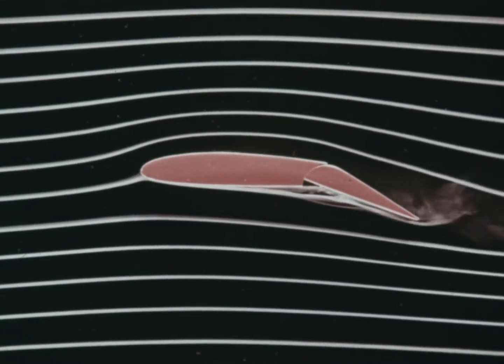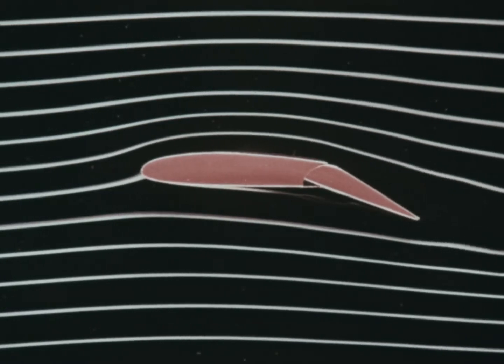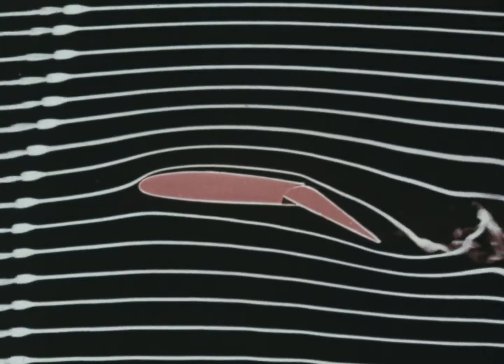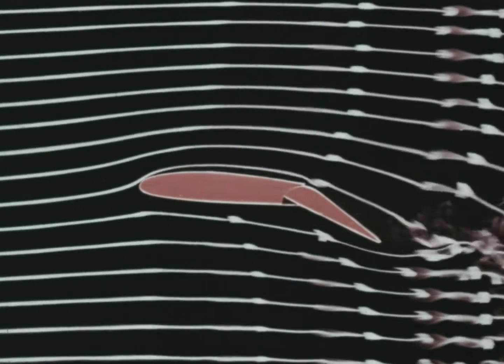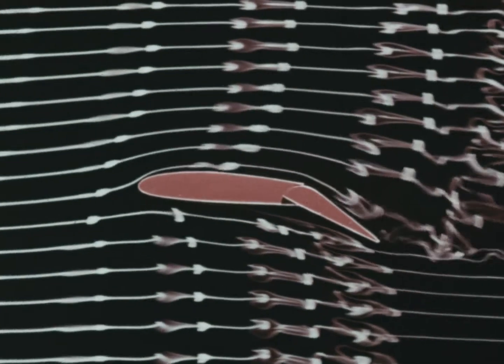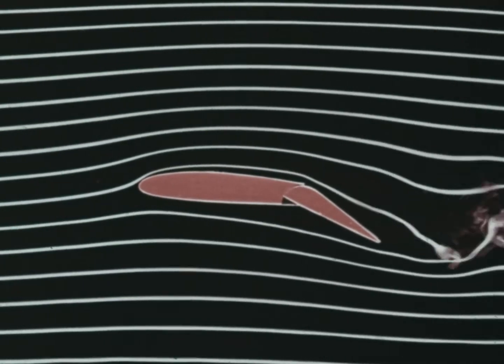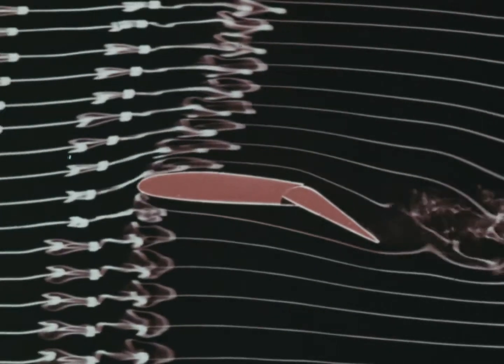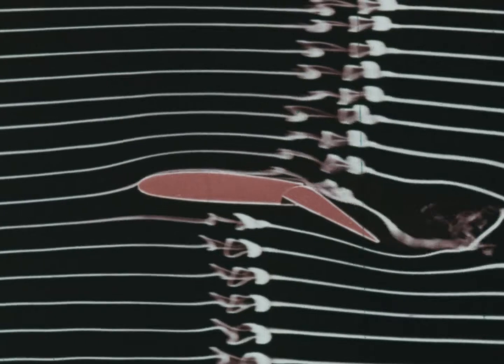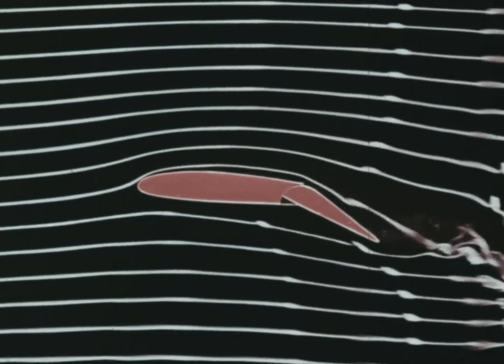This increases the camber of the wing over part of its span. The upper surface of the wing now has even greater curvature, and the airflow therefore moves even faster, while the obstruction caused by the flap below the wing tends to divert more air over the upper surface, where the pressure is now even lower. In this way, more lift is gained without any increase in flying speed.